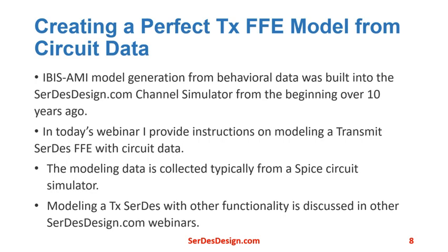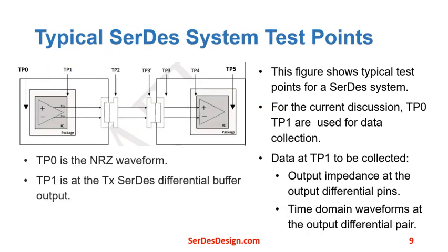In today's webinar, I provide instructions on modeling a transmit SerDes FFE with circuit data. The modeling data is collected typically from a SPICE circuit simulator. The discussion is for a transmit SerDes with an FFE only. Modeling a transmit SerDes with other functionalities is discussed in other SerDesDesign.com webinars.